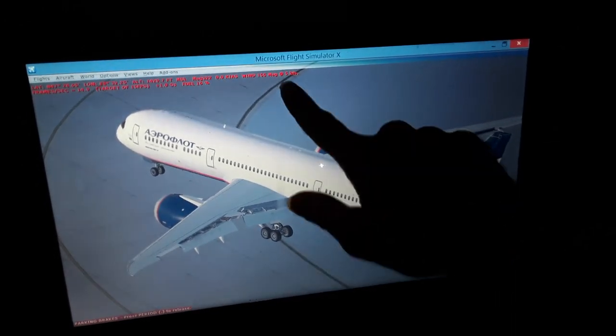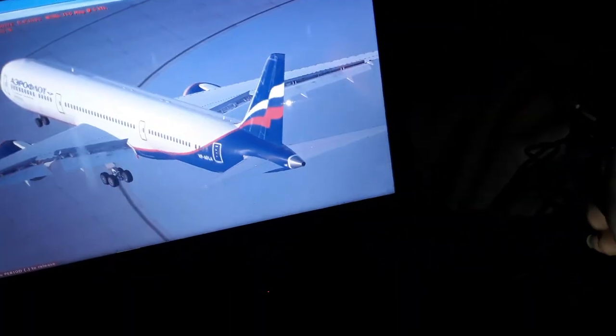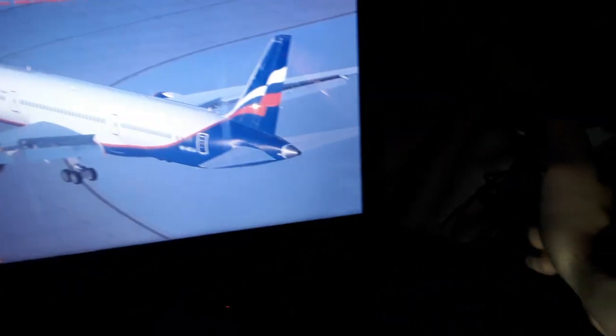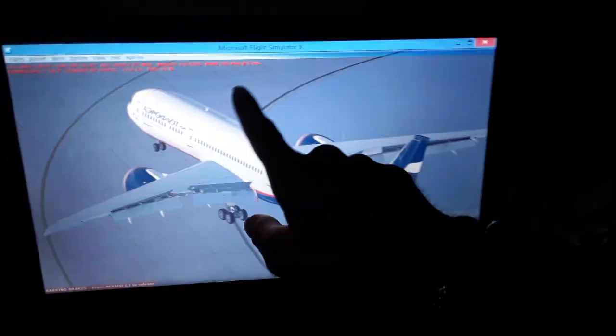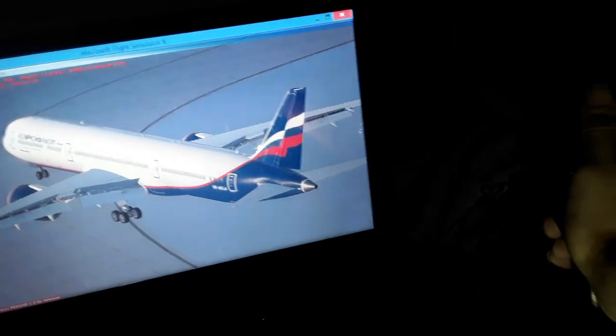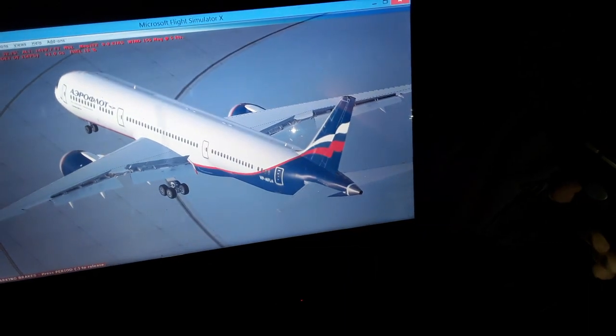We have the center of gravity, the vertical axis, which is also the yawing axis. We can yaw the aircraft left to right using the rudder as we fly, as you can see. So this is the yawing axis through the center of gravity down here. Around it creates a moment that turns the aircraft in the air.